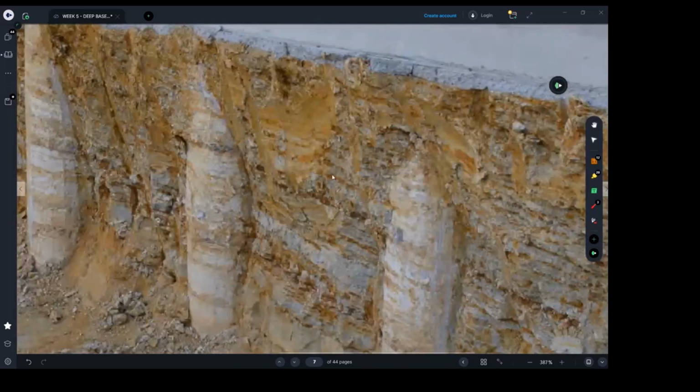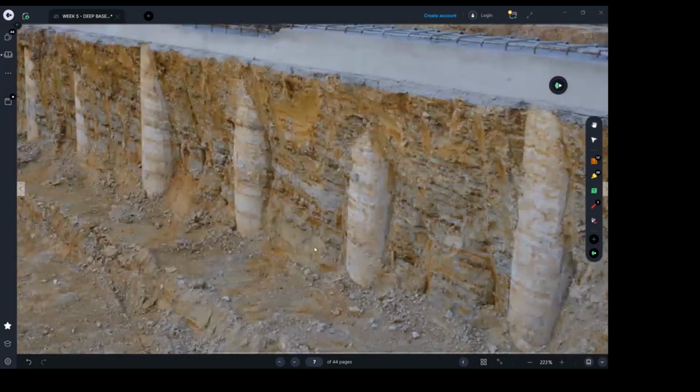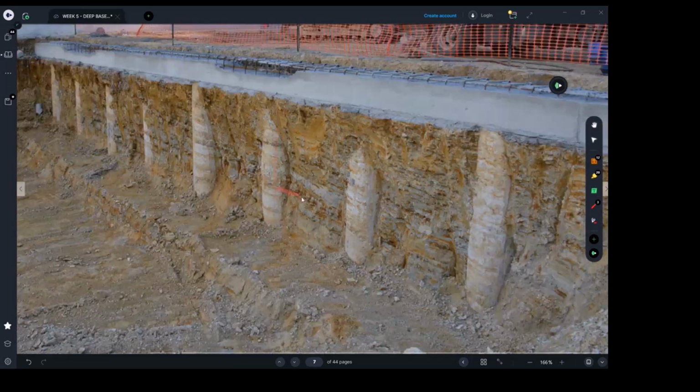It's kind of floating rocks, you can see here. So if you found such a thing going all the way down, you can just go without worrying. Maybe the engineer can tell you, or the soil report can say, no, you can go even farther away. You don't need to go every 1.5 meters. You can go maybe every 2.4 meters, right?